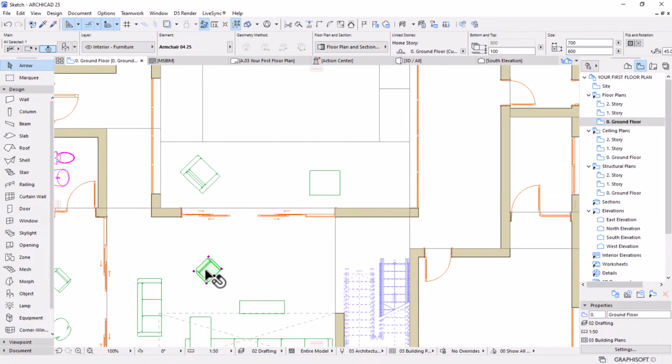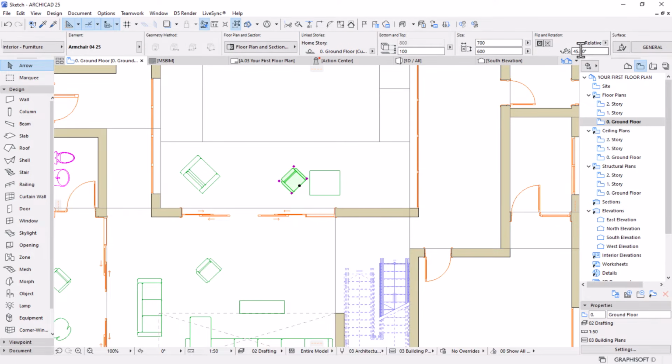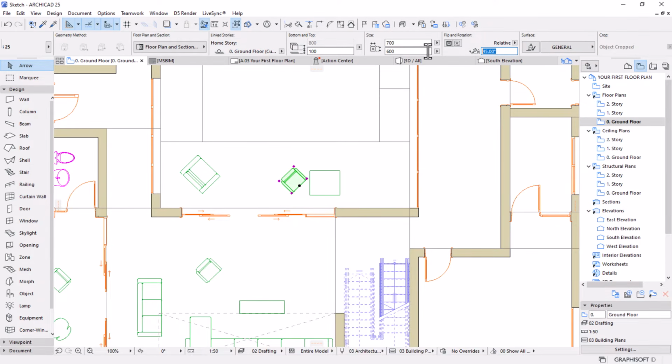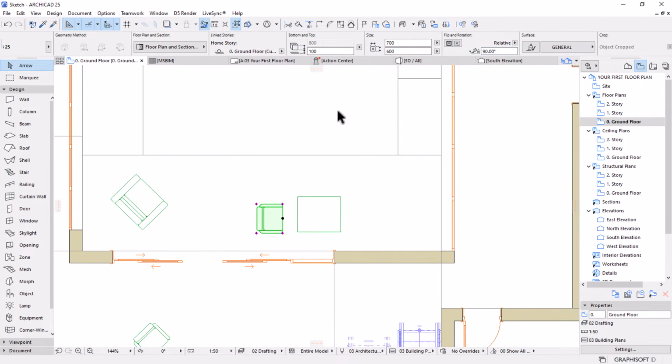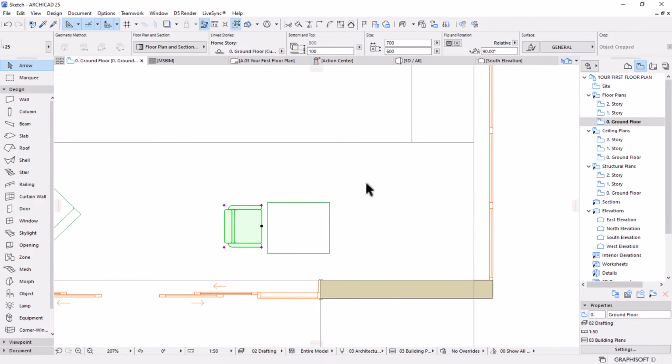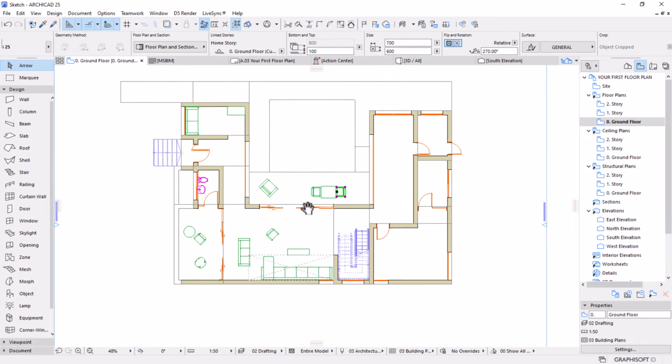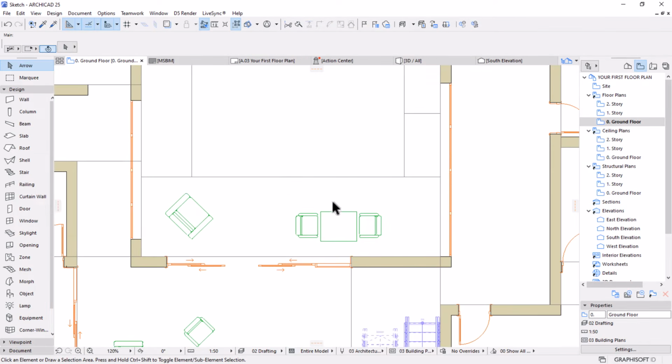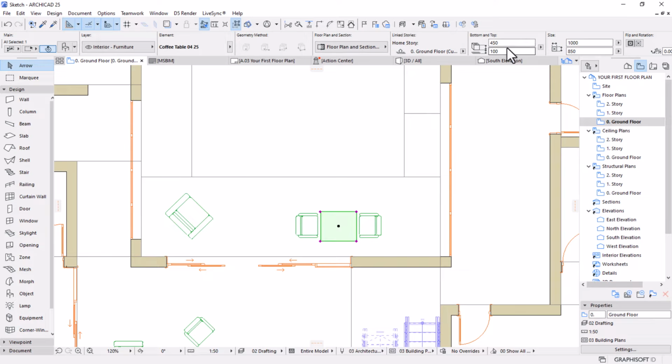I'm going to carry this, Control D, and rotate it. Let's find the rotation on the info box. Rotate to 0 or 90. Perfect. Control D to just put it somewhere there. And then I can Control Shift M to mirror a copy to the other side like that. Perfect. So I still believe I can increase the size of this to be 1.2.